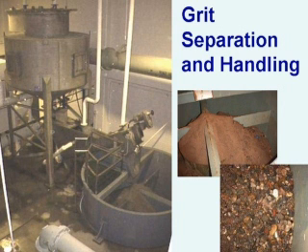You can go in the influent channel, the delivery channels to these vortex separators, and you'll see oil and grease caked on the walls, and you'll see sand and sediment in those channels that get flushed out like waves of sand coming into the system. But if you go into the effluent from these vortex separators in those underground channels, they're clean as a whistle. There's nothing on the wall. There's no sand or sediment that drops out.